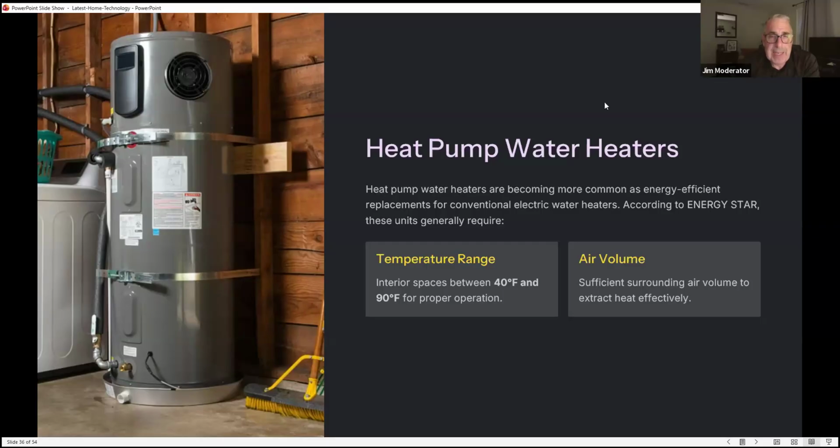And the feedback that I'm getting from a couple of plumbers that I've spoken to is these are okay systems, but in some instances they might not keep up with the demand for the house. So it's something that I do put in my reports now, that this is newer technology and that they should just monitor their hot water during periods of cold, different weather conditions to see if it's supplying the hot water that they need.